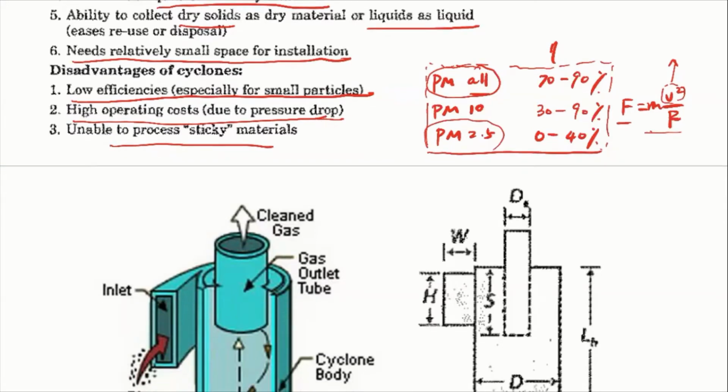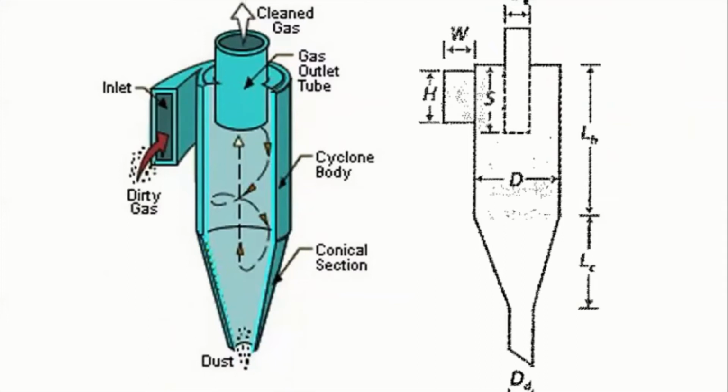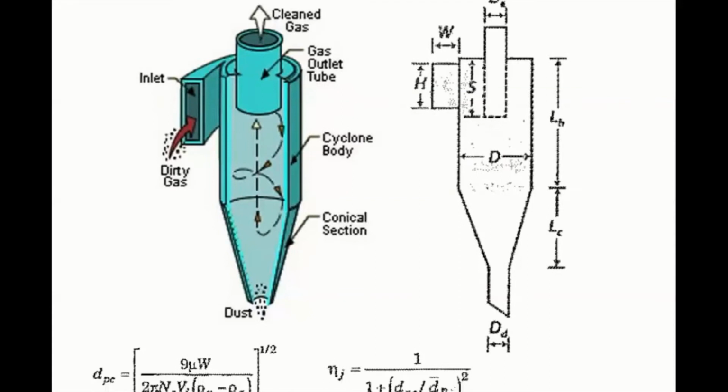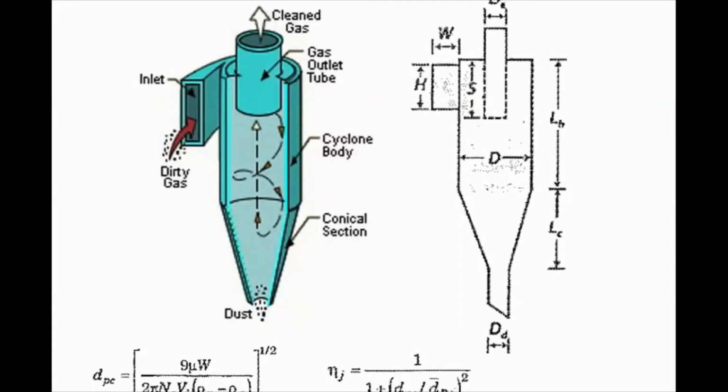Okay. Here I'm showing a few schematic diagrams of the cyclone. You can see that the internal structure is also quite simple. Basically, the air is introduced from the side of the cyclone, and after it enters, it's going to have that rotational movement. I also mentioned that, for example, in that homemade cyclone, you can see that the air actually moves similar to a ribbon, right? It's not going to compress or stack on each other, but the turns have to align very well because the air is not compressible in here.